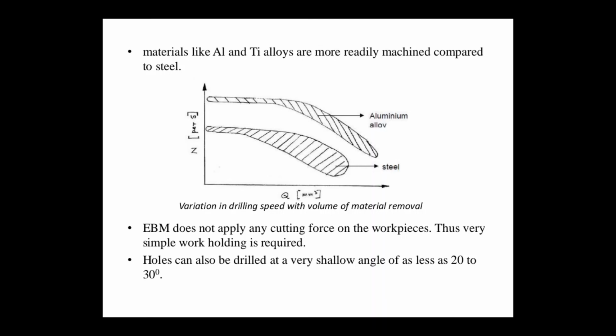EBM does not apply any cutting force on the workpiece. Thus, very simple work holding is required. Holes can also be drilled at a very shallow angle of less than 20 to 30 degree.